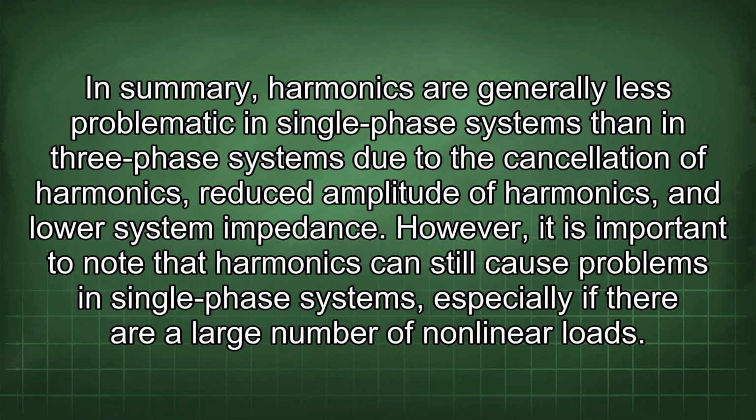In summary, harmonics are generally less problematic in single-phase systems than in three-phase systems due to the cancellation of harmonics, reduced amplitude of harmonics, and lower system impedance. However, it is important to note that harmonics can still cause problems in single-phase systems, especially if there are a large number of nonlinear loads.